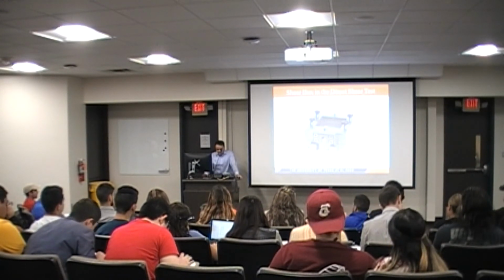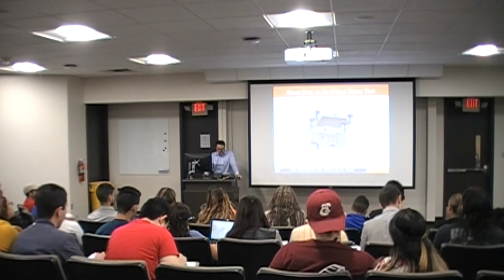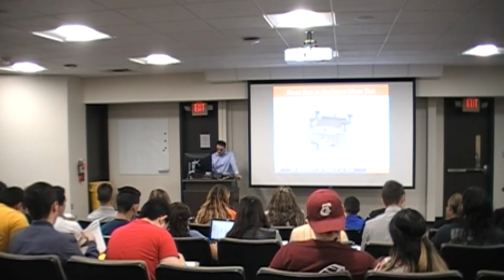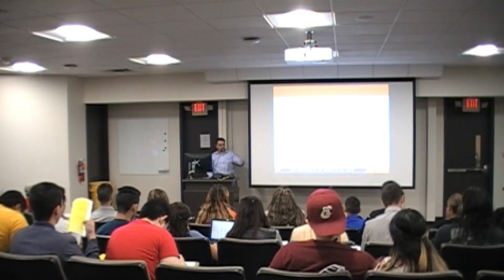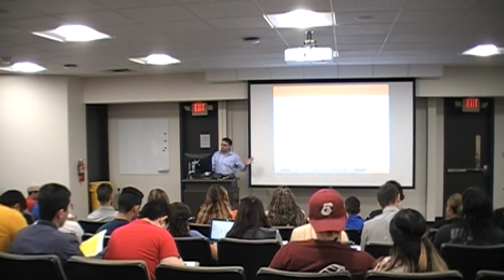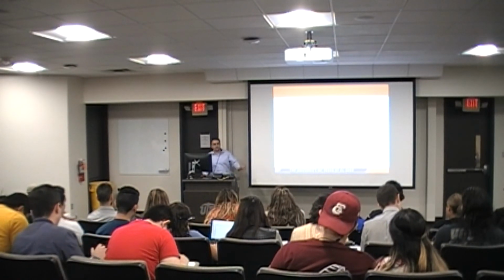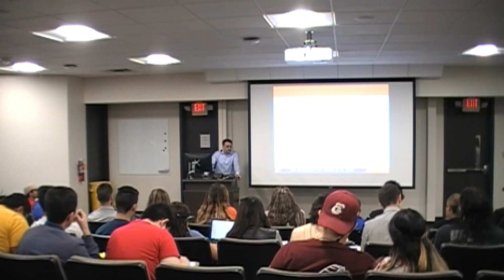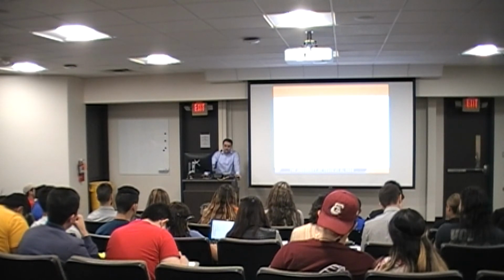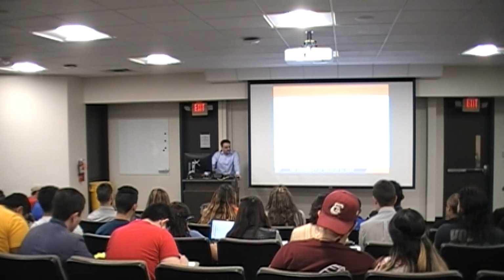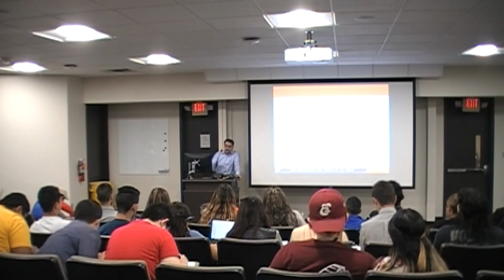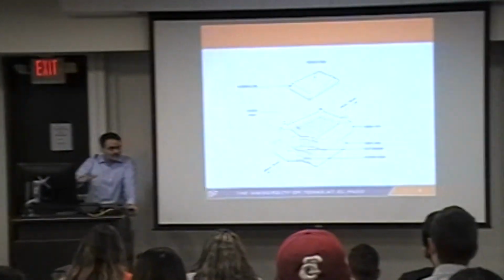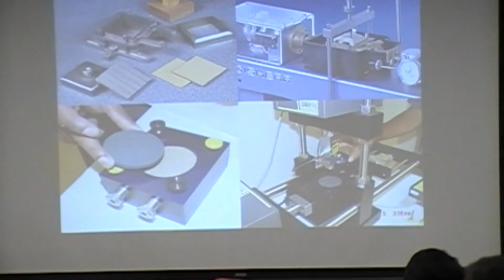All right, so this is the famous shear box that we talked about. It's split in half. It can freely move along the horizontal plane, and you induce the deformation along the horizontal plane. And this is the main disadvantage of this type of test, and that's because of the fact that the failure plane is already determined. We know where the material will fail. The other disadvantage that this test has is the non-uniform distribution of the stresses along the failure plane. So that's another thing that we have to be mindful of.